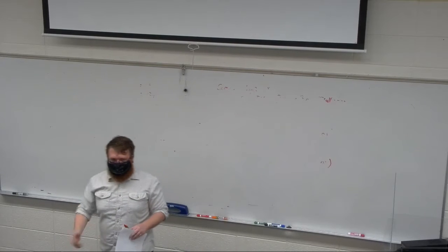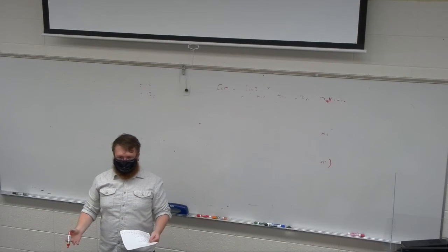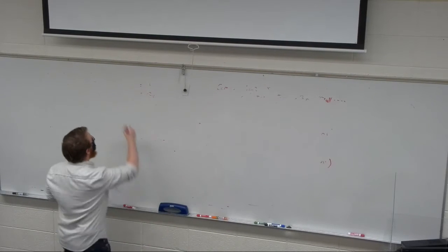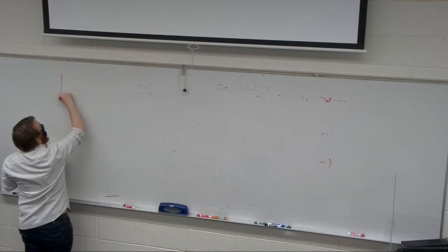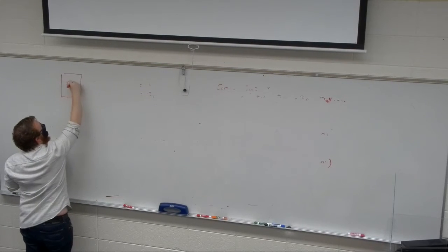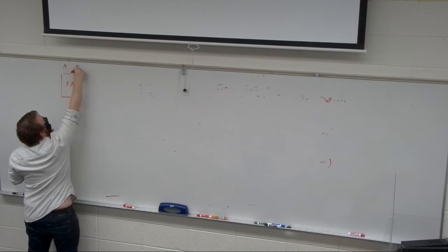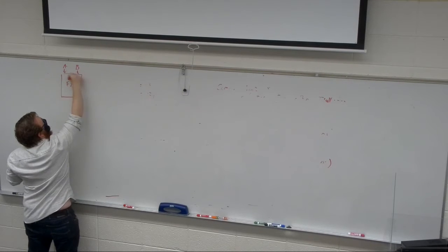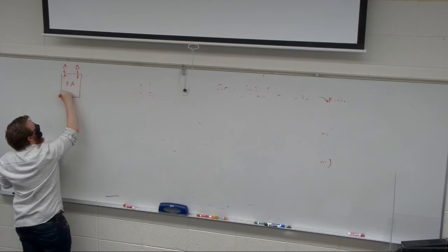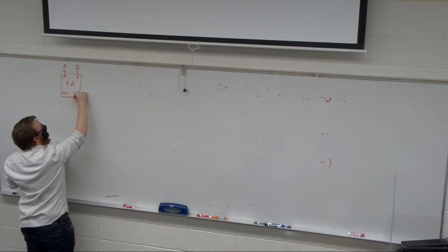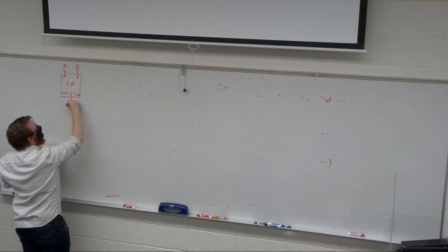When we make a ripple adder, we just start by creating one full adder and chaining them together. So we'd say, all right, this is my full adder. It has inputs, it's going to add A and B, and then it's going to have a carry in, a carry out, and a sum.